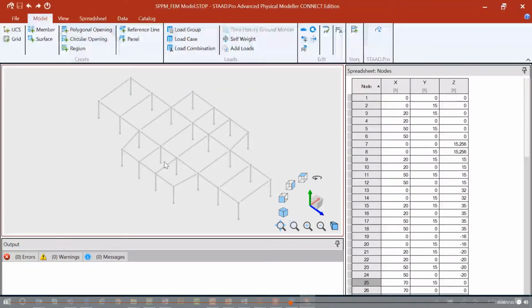Now with the physical modeling workflow, that wouldn't be necessary. You can construct that girder as it would exist in the field, possibly from column to column, and span that infill beam right to that girder without the need to segment that girder at all. Now, if you're using a physical modeling workflow, it's important to note that analysis and design in STAAD.Pro still exist in the analytical modeler.